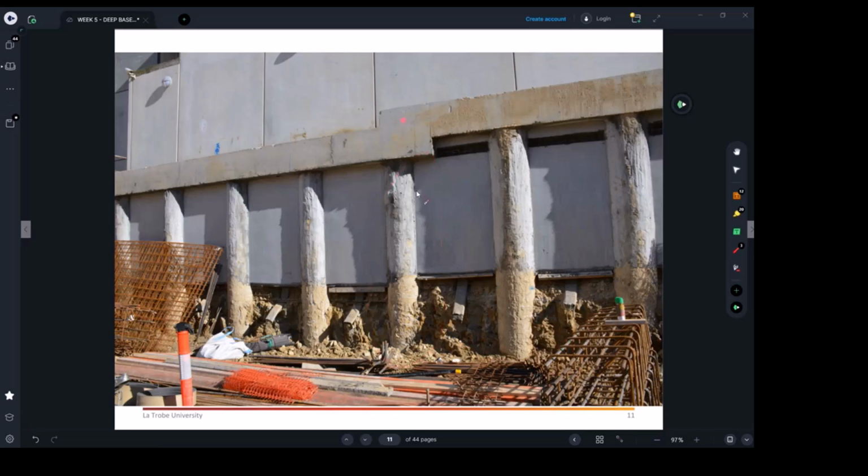This is just a rule of thumb, but the engineers will tell you that there are other considerations which we can use to reduce that 6 meters of embedment. We call it embedment. So the student Ivan, who just mentioned 6 meters into the ground, it can be reduced to 1 meter if we are able to put an anchor here, which I will talk to you about. There are ways where we can put an anchor, like a nail into the ground, if it's possible. We will talk about these kinds of features, details and challenges later on.